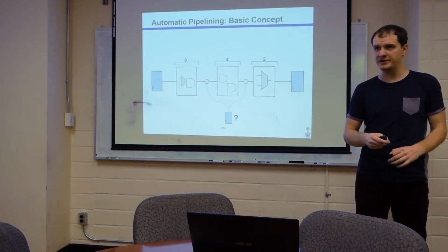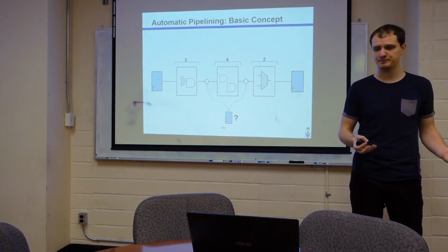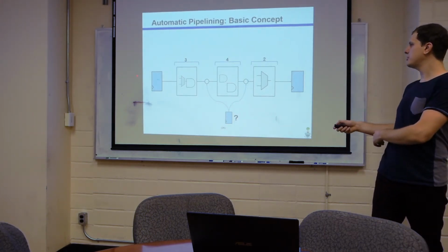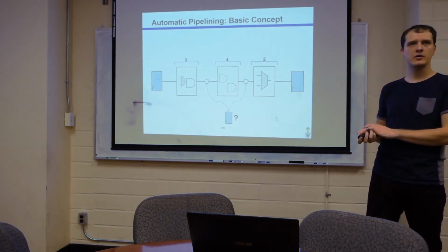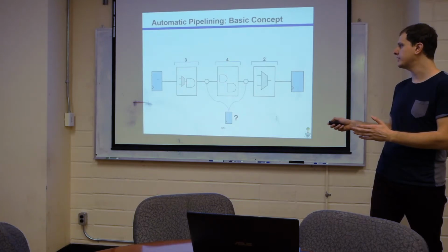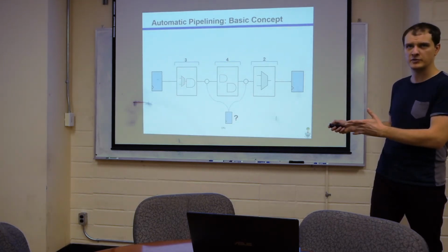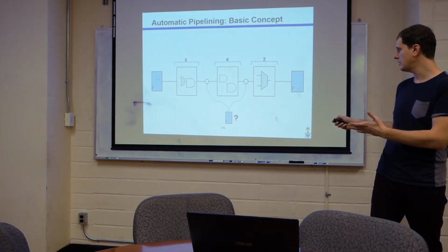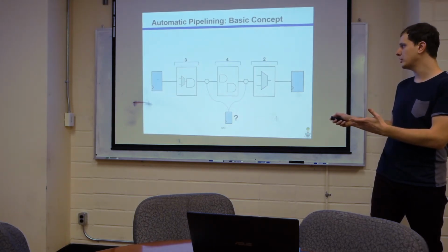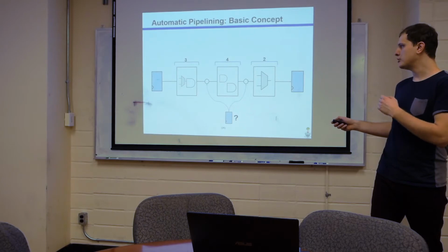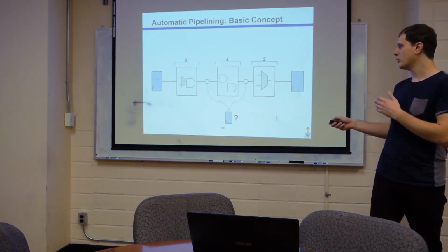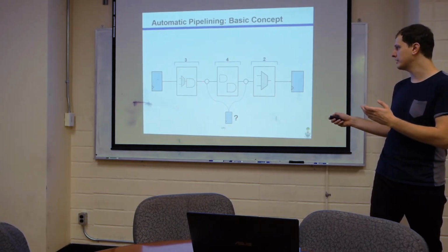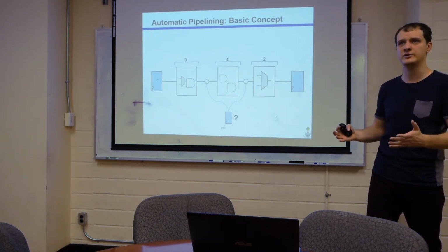Okay, so I'll now explain the basic concept behind how I do the automatic pipelining. Imagine a register to register path somewhere in the interconnect. In the Genie view of things, there exists no raw logic between these. There's structure, there are modules. And each of these has an internal combinational logic depth through it. Genie's only able, by my design restriction, to insert registers between modules on these links, so I can't actually pipeline the interior of these. This provides a certain minimum granularity to the pipelining problem.